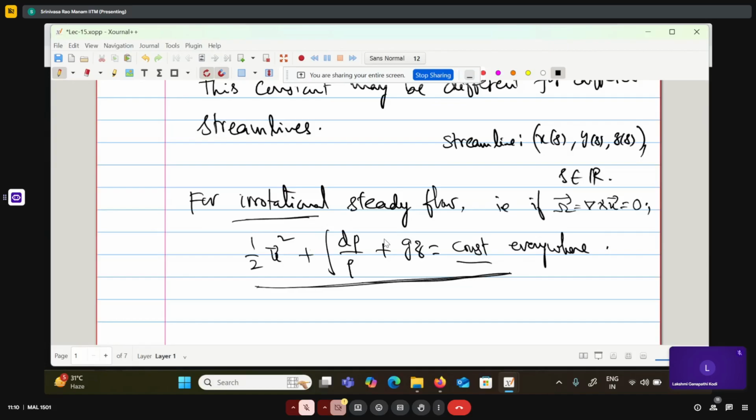No, I think what we have done is basically, you have taken the momentum equation and you have written it. Did we use anywhere del dot u equal to 0? We have not used it, right? Basically, we have not done anything except rewrite, and now we put the condition that irrotationality will remove the term. If you use del cross u equal to 0, that will give you nicely your Bernoulli equation.